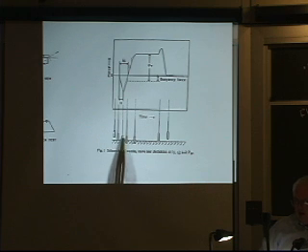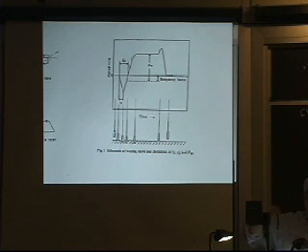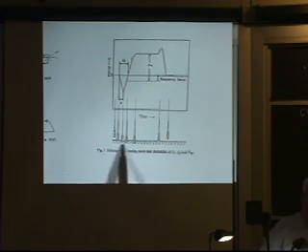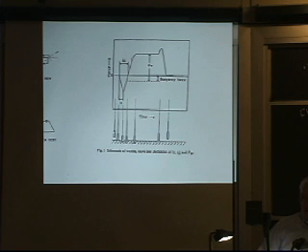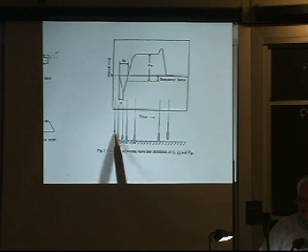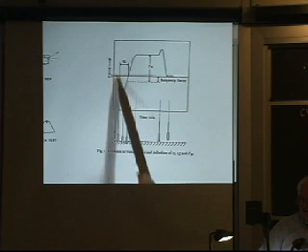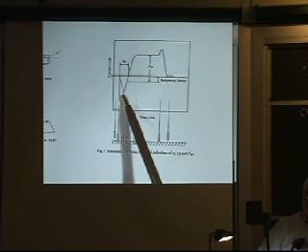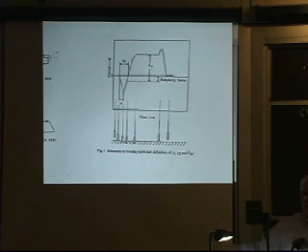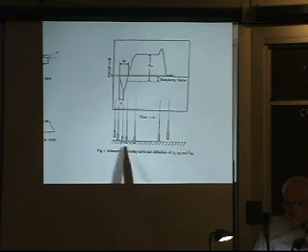There's no wetting. Initially, as it tries to go beneath the molten solder surface, it's not wetted, and so surface tension is creating a contact angle that actually is making it float. And so the weight of this thing actually decreases. And the further you push it in, the lower the weight, the more it's floating. You're basically just taking a rubber ball, a balloon, and pushing it under the water, if you will, in this case under the molten lead tin solder.